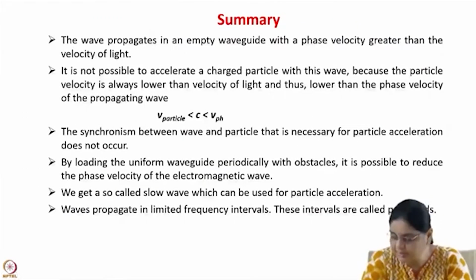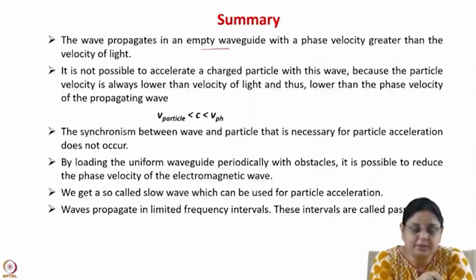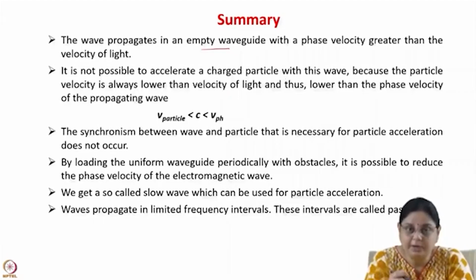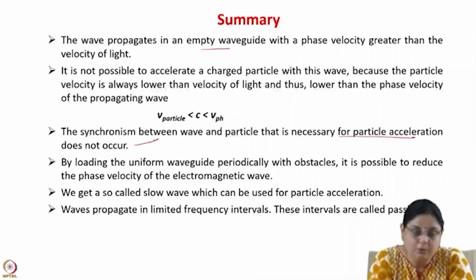Okay, so let's summarize whatever we have learned today. The wave propagates in an empty waveguide with a phase velocity which is greater than the velocity of light. So it is not possible to accelerate charged particles with this wave because particle velocity is always lower than the velocity of light. The synchronism between the wave and particle will not be there. So synchronism that is necessary for particle acceleration does not occur in a hollow waveguide.